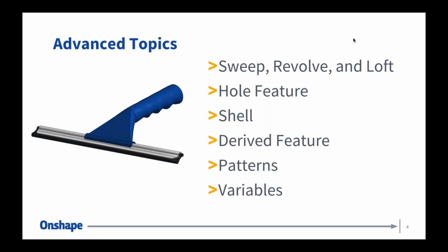Let's say I'm designing a part and I have this wall thickness, and I'm constantly entering in 3 millimeters in many different sketches. It's the standard wall thickness I'm going to use throughout the whole part. If I enter in 3 and 3 and 3, and then we realize, oh no, my uniform wall thickness should be 4, then I've got to go back to all of those sketches and change all those values to 4. It's not a very intelligent way to design the model because I have just these static values. That's where variables can be used. I can create a variable, set the dimension equal to the variable, and then change the variable and control everything in one place.